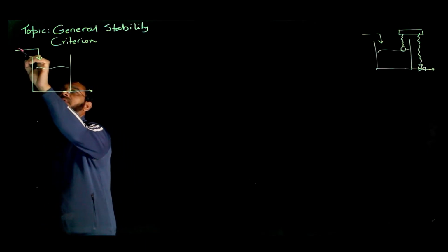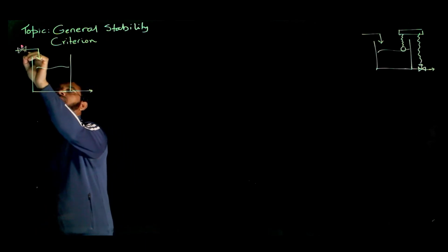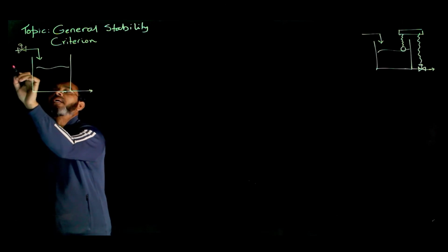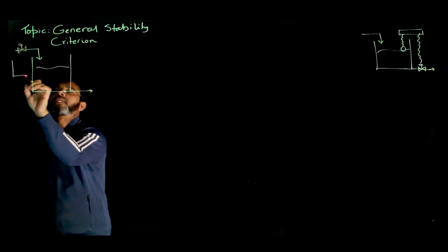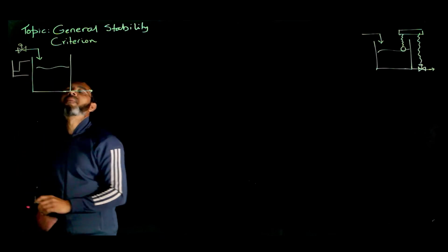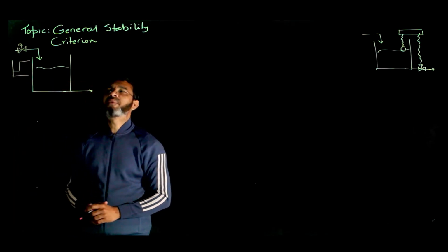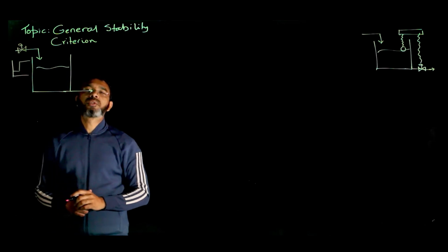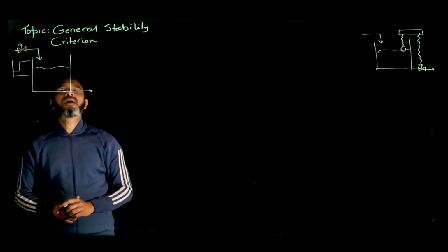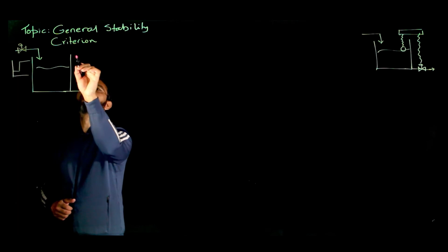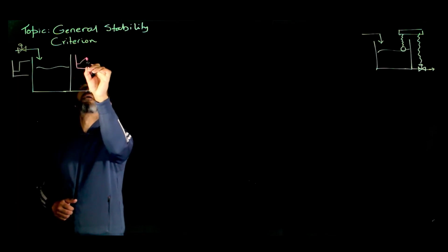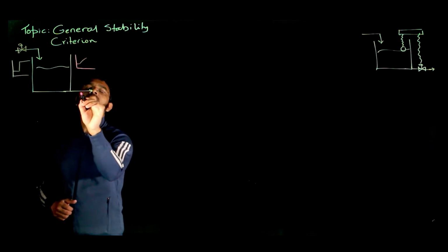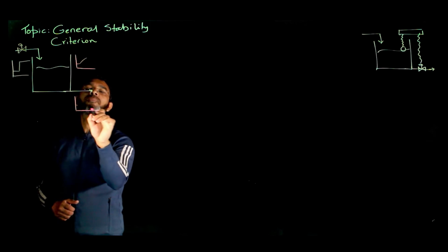in this inlet flow, so whatever was the inlet flow here, if we just increase it in a step manner, what happens is that the level starts to go up, and when the level starts to go up, the outlet flow also starts to go up.